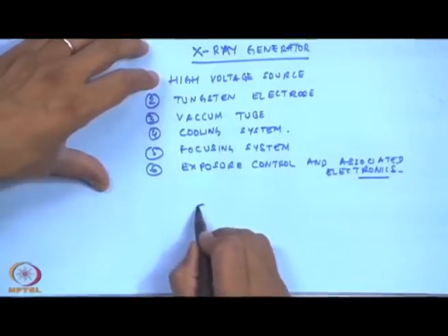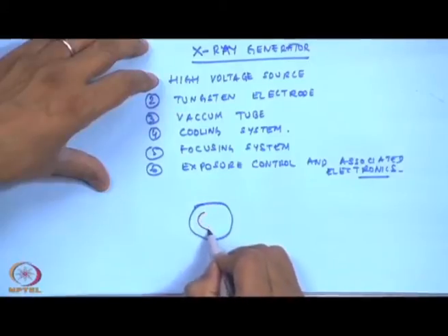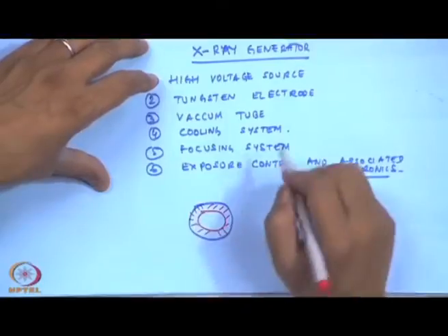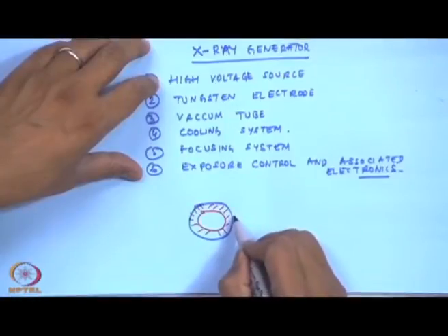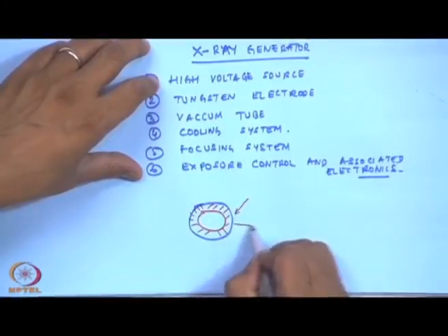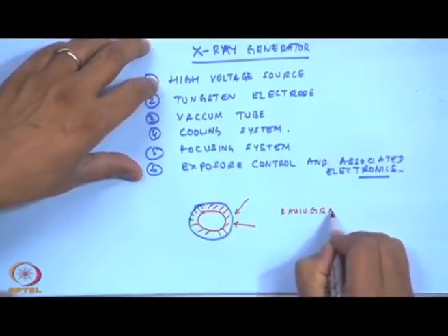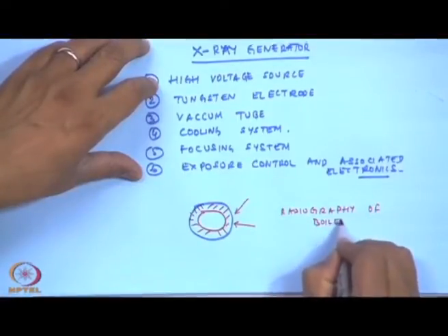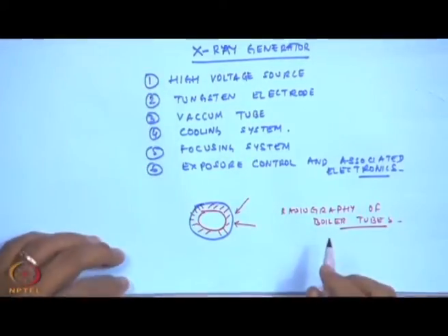But the component, particularly in NDT, suppose we have a boiler tube, okay. Suppose there are some scale formations. I had mentioned to you regarding the ultrasonic to measure the thickness, but they can have an X-ray exposed to this. So, radiography of boiler tubes is one application where X-rays are done.